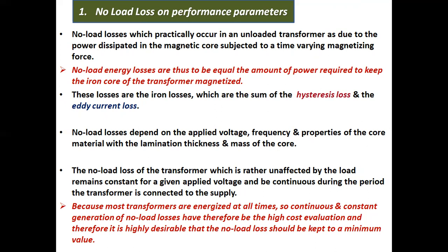The no load loss of the transformer, which is unaffected by the load, remains constant for a given applied voltage and is continuous during the period the transformer is connected to the supply. An important point to be noted, because most transformers are energized at all times.